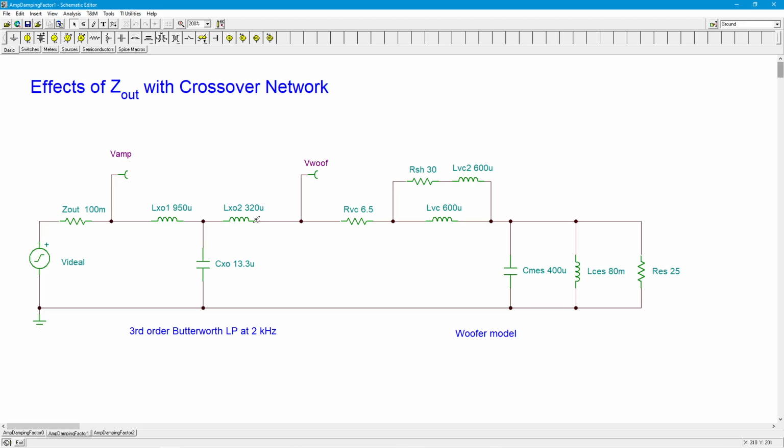If you have really long loudspeaker cables, especially if they're small diameter, in other words, large AWG, large gauge cables, like a 24 gauge cable, that's going to exacerbate the problem as well. So that's another argument for keeping your cables relatively short and a decent gauge. Depending on how short they are, maybe a 14 gauge, 12 gauge, something like that would probably work fine.